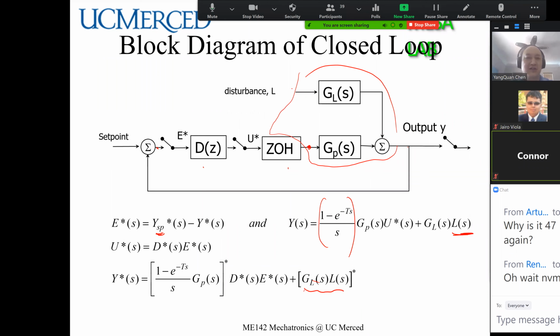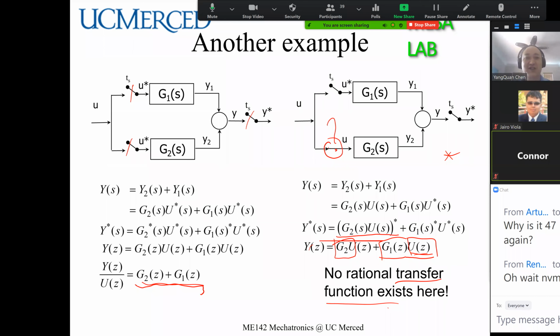So here, this is continuous. And this ZOH is to turn all those dots into continuous. So that's the whole picture. This is ZOH. And you should do this Z transformation of G(s) considering this ZOH by doing this star. So having this type of sampling idea will not make you confused. Like, if you don't have sampling here and you do it this way, then it may not have a transfer function.